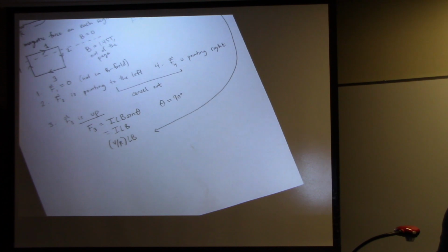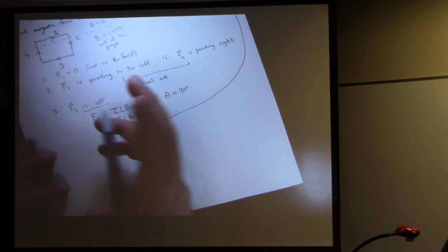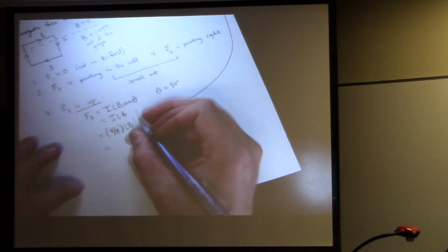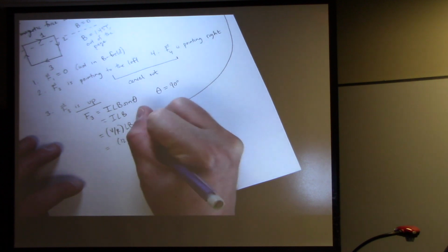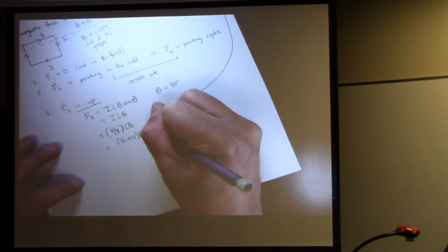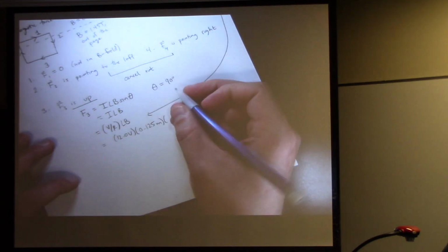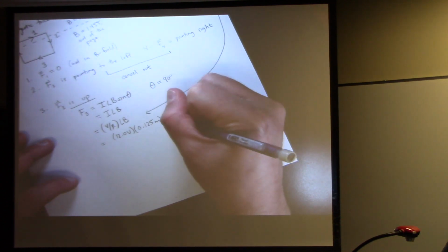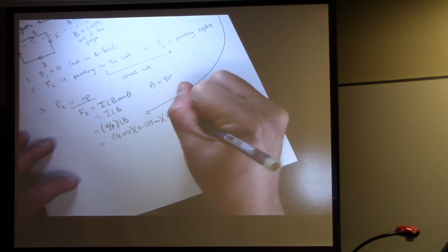So now what can we do with this? We can put a number to it. How much force is the magnetic field exerting on this loop of wire? Well, it looks like on top I have V, which is 12 volts. I have L, which in the picture was 12.5 centimeters, or 0.125 meters. And then the B field was, what was it? 1.45 Tesla.